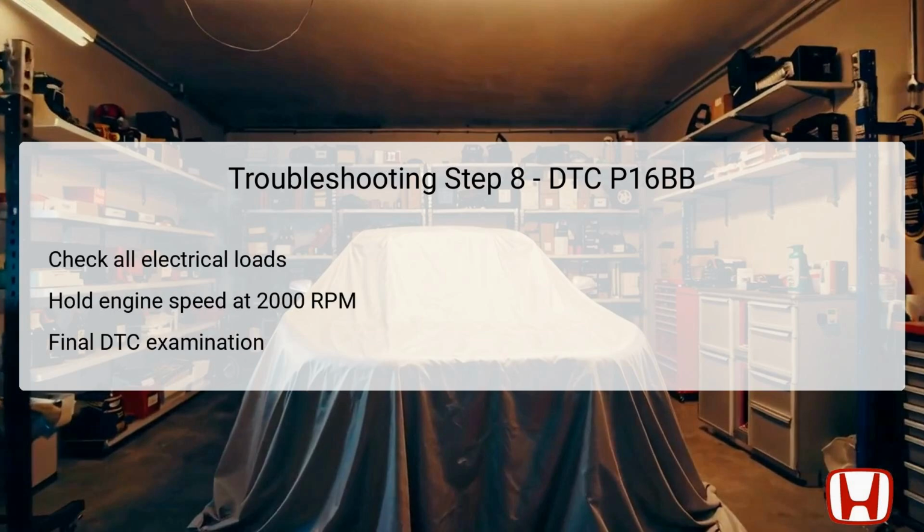In this step, the technician will echo previous tests to determine whether the issues have been resolved. The engine should be started and allowed to reach operating temperature with all previously defined electrical loads active, including maximum AC, blower speed, headlights on high beam, and rear window defogger. Hook up the HDS once more, checking for pending or confirmed DTCs.